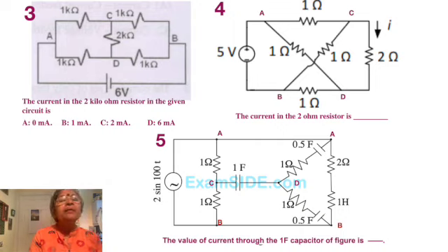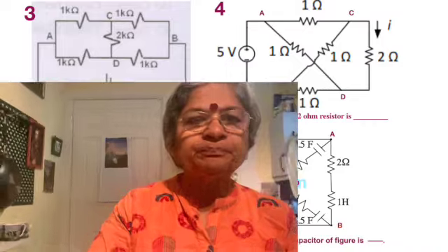They are all the same. So we see that no current flows through the 1 farad capacitor. So that's what is asked. Though currents do flow through the 2 ohm and 1 Henry circuit that is connected between A and B. Since only the capacitance is asked, we realize that the current is equal to 0.